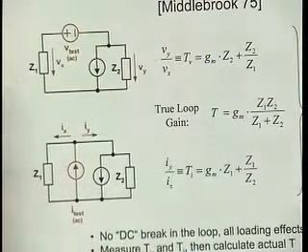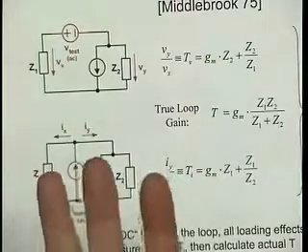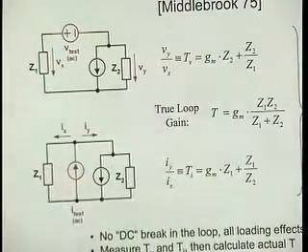And you actually can run all of that in one single SPICE deck. You don't need to run SPICE twice. For that, you typically will use the alter statement. Who has ever used the alter statement? Okay, two or three. So now you all have an opportunity to familiarize yourselves with the alter statement.